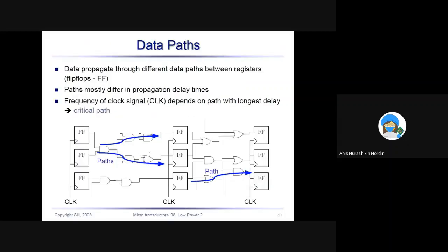So this is the path. If you are running a race, the gatekeeper of the race here is Mr. Flip-Flop number 1, and the finishing line is controlled by another flip-flop. And if you have to run another race, there will be another flip-flop. So your combinational logic will be put in the middle. Combinational logic is the gates that are not involving the clock, such as NAND, NOR, XOR, or inverter. These are known as combinational logic. Flip-flops are the sequential logic, or the gates that have timing.